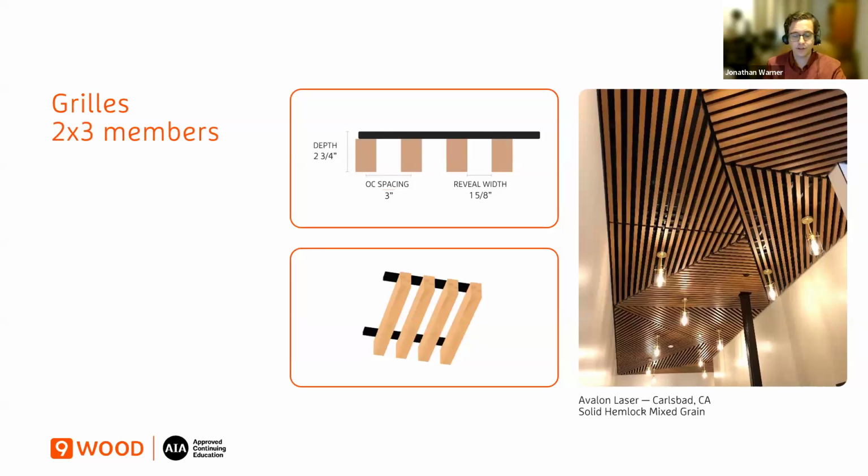I like this photo because it highlights that with Division 9, you're working with an acoustical sub and on some occasions a wood ceiling specialist. Together they can provide a lot of different custom applications like this. In a lot of situations, they're field cut, and the manufacturer coordinates install drawings and maybe field instructions, because schedules often don't permit getting all the as-builts. With the proper setup with these specialists, you can get results like that in the photo with angular cuts, and provide a variety of different nominal panel sizes that get better yield and can be cut in the field by an acoustical sub.